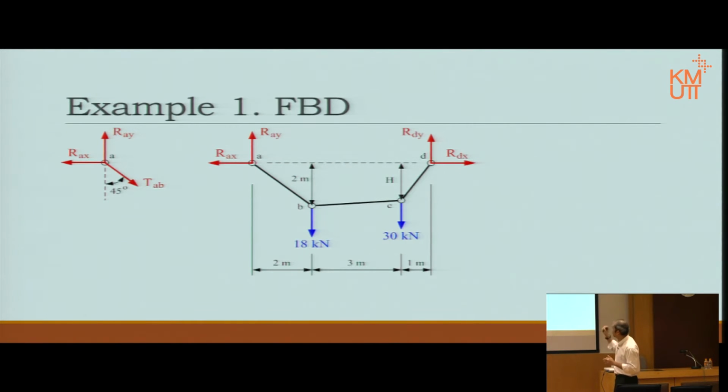So basically, in these two pictures, we have 5 unknowns. On the right-hand side, we have three equations: sigma Fx, sigma Fy, sigma moment. On the left-hand side, we also have three equations, but sigma moment is always 0 because it's just a point. So you have 0 equal to 0, which is still rotational equilibrium, but the equation is not useful in our calculation. This is like a joint, a point, a kind of particle type, so in effect we have only two equations: the summation of force in the x direction and in the y direction. So 3 equations plus 2 equations is 5 equations. 4 unknowns plus 1 more is 5 unknowns. With 5 equations and 5 unknowns, we should be able to sort it out. Let's see how.